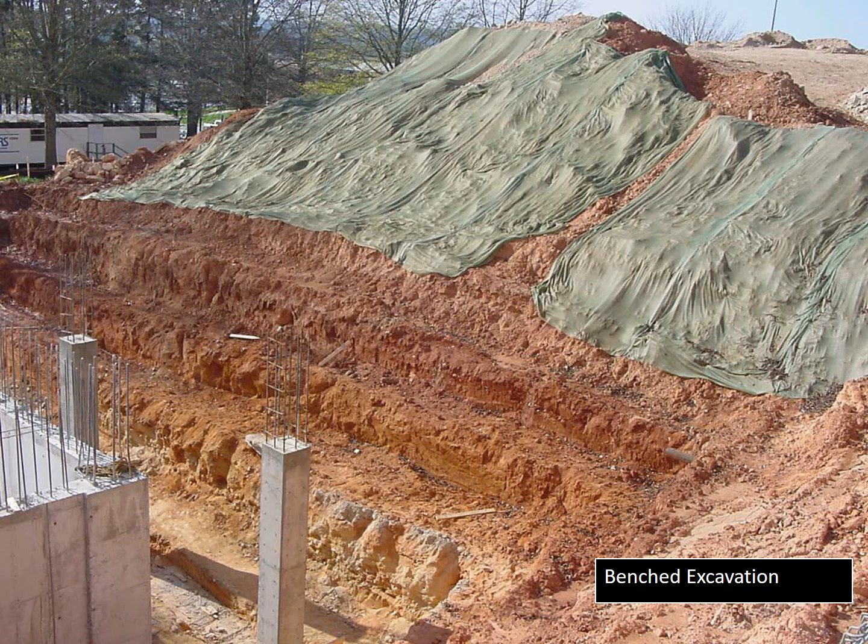So here's a look at a benched excavation. You can see it looks like a series of benches on the earth. You go up a few feet, then horizontal a few feet, keeping it flat, kind of like terraces. The idea is these are used mostly in sandy soil. There's quite a degree of angle there, maybe 45. There really ends up being more than a 45-degree angle. And the idea is to keep this all from caving in.